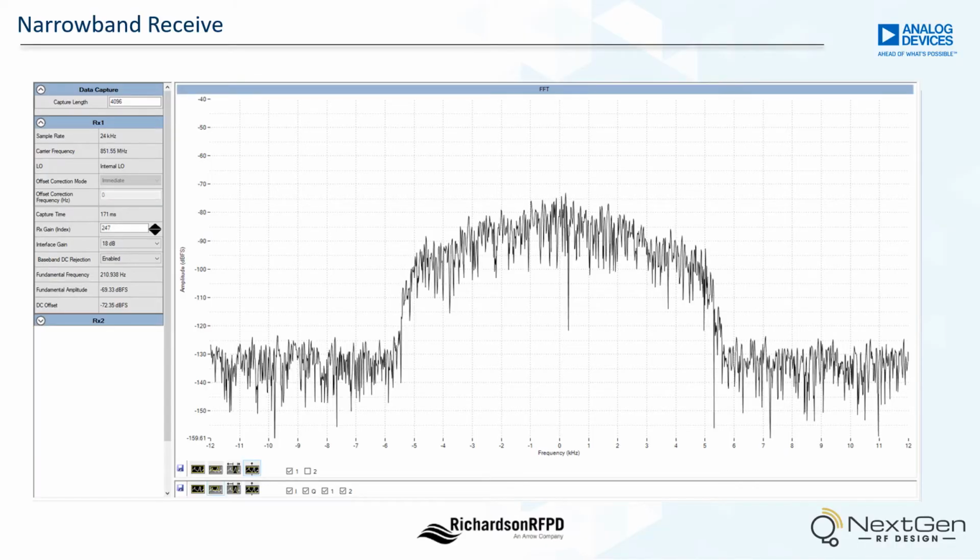For optimal performance, the ADRV9002 can be configured to receive a single 12.5 kHz channel with both DSP and analog filtering. Further, the high dynamic range receiver can coexist with adjacent channels by having over 150 dB per hertz dynamic range without using AGC. And to avoid DC offset issues in direct conversion receiver architectures, a low IF mode is possible for narrowband signals.